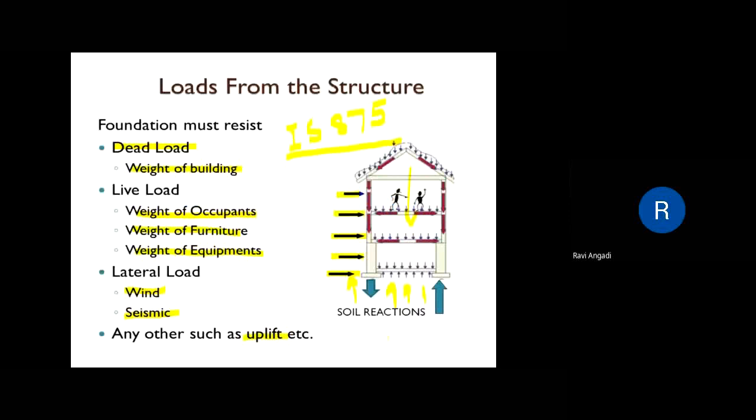And apart from these forces, there are other forces also acting. That is snow loads. Snow loads occur due to the accumulation of snow on the roofs and exterior flat surfaces in cold climates. And the unit weight of the snow is usually taken as 1 kilonewton per meter cube. That is to be considered if the building is constructed in cold areas. And water pressure, as I discussed, is also acting. Like earth pressure is also acting.